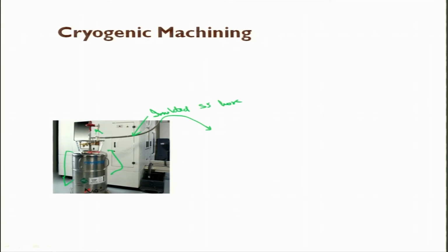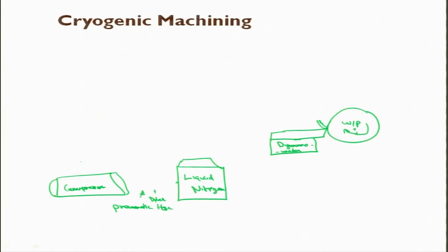and here even we can have a flow meter to control the flow. Here the flow meter could be there. And this also is connected with my compressor that is producing liquid nitrogen. So, this pneumatic hose is connected here. So, in between I have a dryer and a pressure regulator.